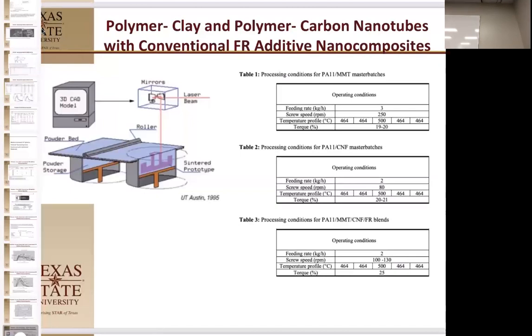So at the feed throat, it's going to be 464 degrees, and that's to get it to start melting and pulling it in. Then it's going through the maceration blades, and that's about where you're adding your clays in the second zone. You add your clay, add some powder to it, and then it goes through your high shear zone.